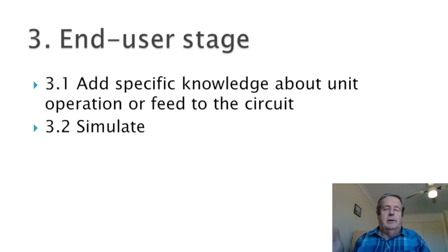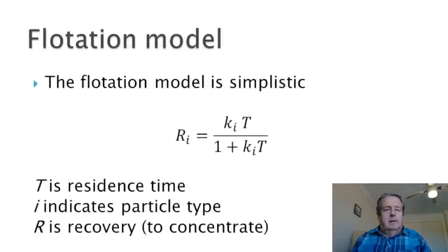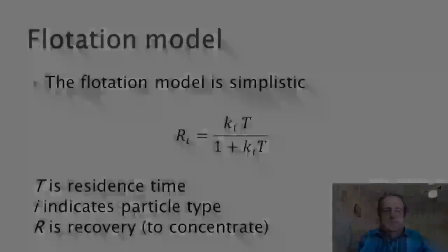So in the case of flotation, he might change the kinetic rates, he might change the feed, and then he simulates. In this particular case, the flotation model is simplistic, just recovery going to the concentrate is this function here in terms of the kinetic rate and the residence time, but we don't have the residence time, so K times T is a combined value.